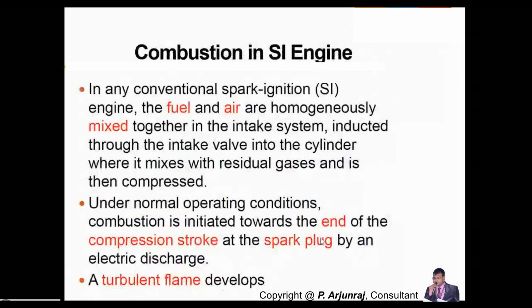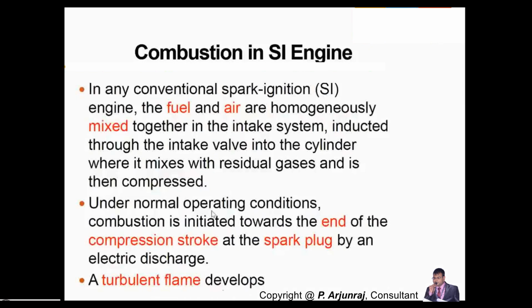Okay, we will see the combustion in the SI engine. Now we'll go to the topic. I have mentioned that the fuel and air is going to be a homogeneous mixture in the case of an SI engine. When it is inducted through the intake valve into the cylinder, you are going to get the residual gases, and it is getting compressed. We have seen the valve timing diagram. The piston moves from TDC to BDC, where the air fuel mixture comes in, and when it moves from BDC to TDC, it gets compressed.